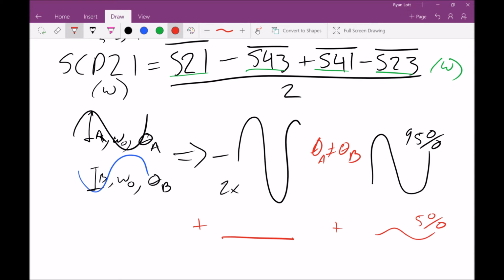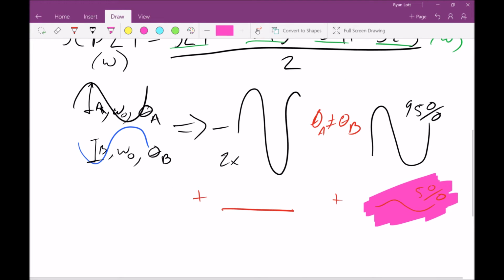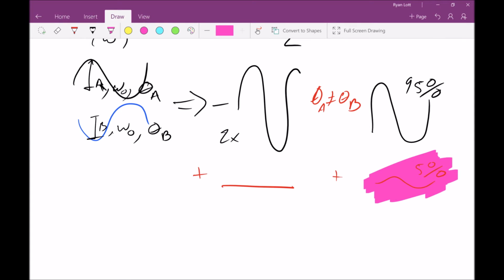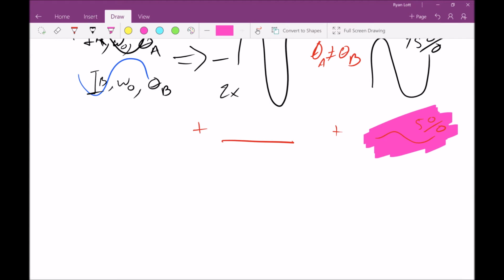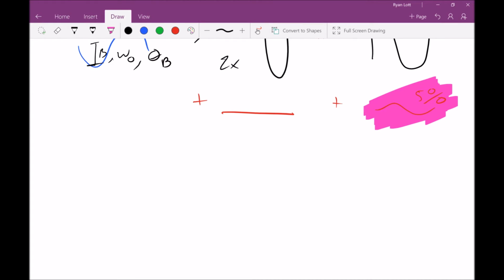And this 5% common component right here can lead to very disastrous results if it's not controlled in a reasonable manner. It can radiate if it's in the right environment. It can bounce around and cause all kinds of intersymbol interference problems if it's converting back and forth between common and differential, and many other things. So that was, I guess, again, a second primer on this.